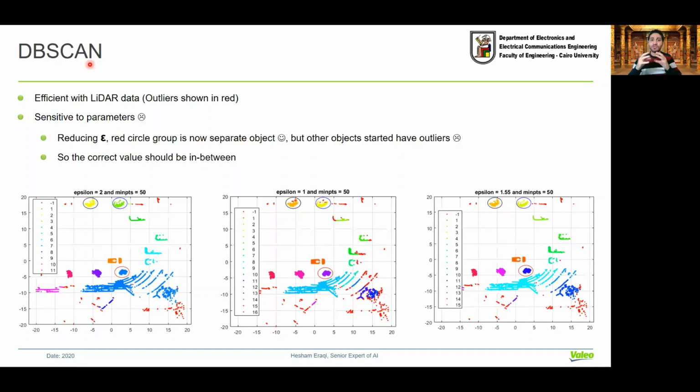To do this, the radar sensor is transmitting sound waves, but the laser scanner is achieving the same task by transmitting laser beams. So a laser scanner sends a laser beam in some direction and records the time of transmission. And this beam will eventually hit an obstacle and be reflected back again, and the sensor receives it and records the time of the reception of such echo or such beam. And by having the transmission and the reception time, the beam round trip time is calculated. And because we know the speed of light, we can estimate the distance between the sensor and the obstacle, and we can represent this in the 3D space by a dot that tells us there is an obstacle at this location.